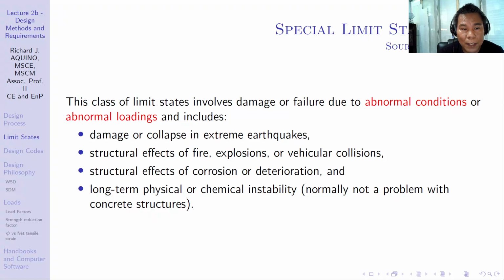For the special limit states, we have this class of limit states which involves damage or failure due to abnormal conditions or abnormal loadings and includes damage or collapse in extreme earthquakes, structural effects of fire, explosions or vehicular collisions, structural effects of corrosion or deterioration, and long-term physical or chemical instability, which is normally not a problem with concrete structures.